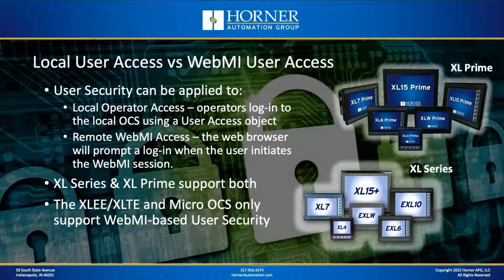XL Series and XL Prime can support user security as it relates to both local operator access from the touchscreen as well as remote WebMI access. Our lower end products, like the XLE and XLT and the micro OCS families, they only support WebMI-based user security. For those, you'll have to continue to kind of roll your own local user security, but that's not that difficult. It's just not what we're going to be talking about during today's topic.